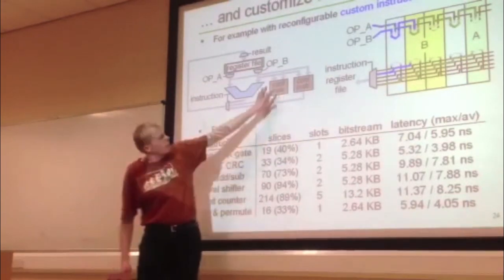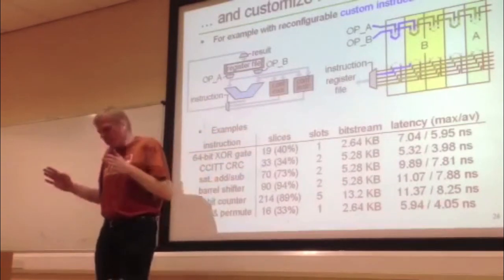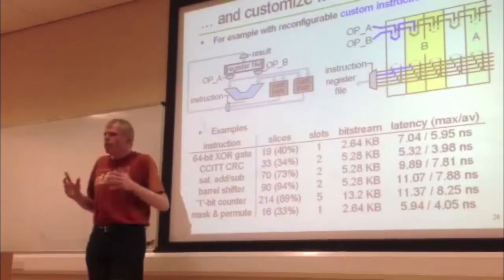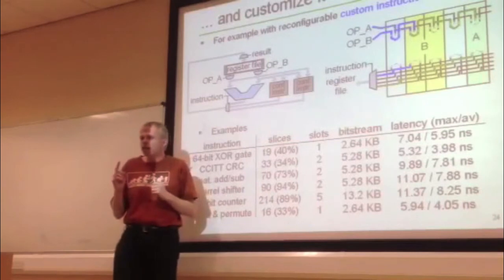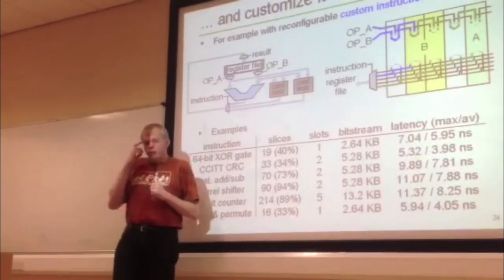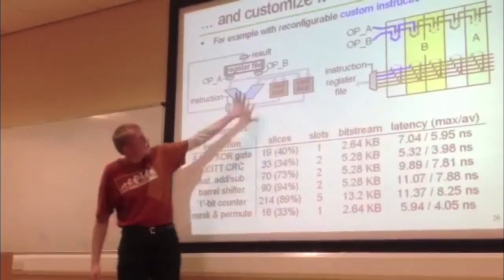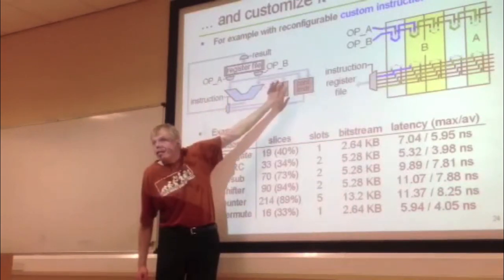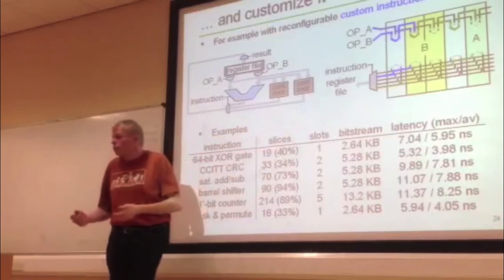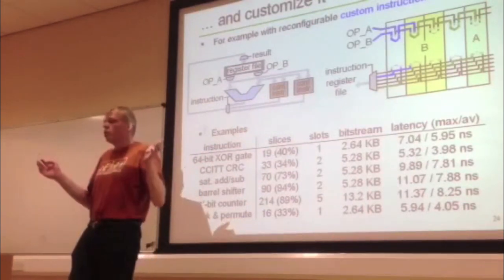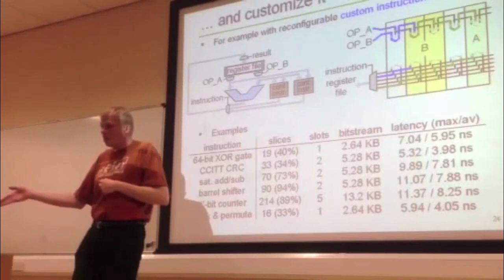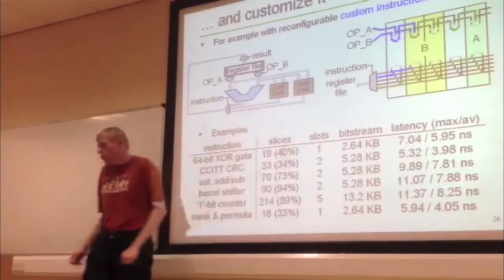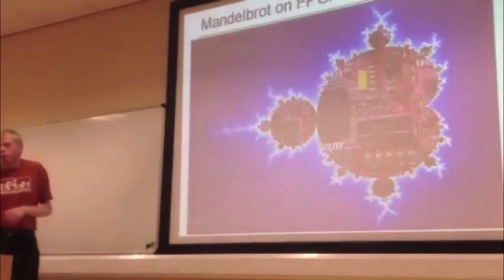And this customized instruction is the best of the RISC world and the CISC world. So the nice thing with the RISC is it's small, lightweight, but fast. And CISC allows you to do a few more complex things. And here the idea is, okay, you keep it as lightweight as possible, and only the things where you know I need, then you put in. If you have a CISC processor like your x86 machine, it has so many instructions that if you would disassemble your program, a lot of these instructions are never ever used. And here you can just put in what you really need. Okay, so that would be processor design.